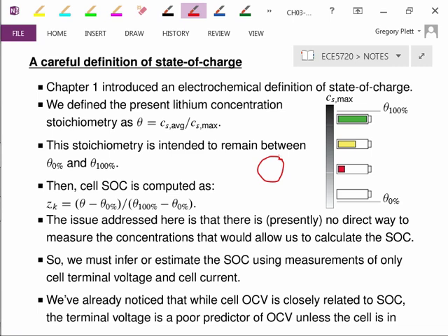And they could have no lithium in the structure at all, and it doesn't necessarily degrade the structure, or they could completely be packed. They could be completely saturated with lithium, and that doesn't really affect the structure at all in many cases, or at least there's some range of lithium saturation, lithium usage that has no impact on this structure and can be used to store lithium in one of the electrodes.